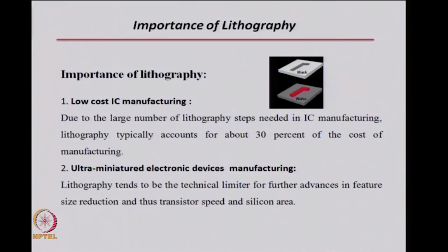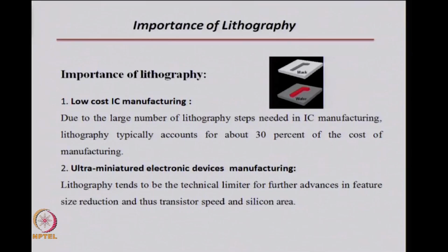The importance of lithography today especially comes from our IC industry. ICs, or integrated circuits, are the key in all kinds of computational devices, whether they are computers or any other electronic devices being used today. The manufacture of ICs requires several lithographic steps, and lithography costs about 30% of the total cost of manufacturing of that IC.